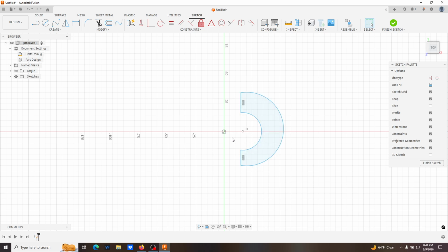I think the thing when it comes to putting constraints in your sketches is you want to put just enough. So I'll go ahead and put this here, select those two points, make them coincident, and then I will put my point here and make that coincident. I think it's always good to anchor your sketches to the origin point, just because things can float and move around. And while I could definitely put these coincident to each other, I'm actually just going to use construction lines here.